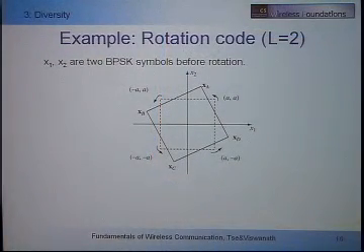Instead of sending, let's look at this picture. So I'm a pretty geometric guy. And if you look at this picture, okay? If I don't do any coding, then what I'm doing is I'm sending 4 points here, okay? By the way, just to clarify, here I'm sending two BPSK symbols over two coherence times here. So these are not I and Q phase, just to minimize the confusion. This is just two BPSK symbols over two different coherence times. Okay? So I have these 4 points here, and these are my 4 possible values that x1, x2 can take on. Each one is plus or minus a.